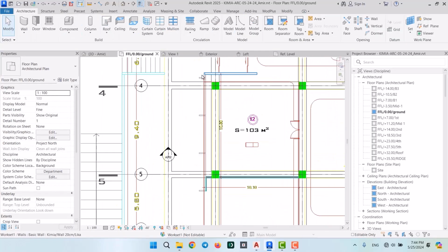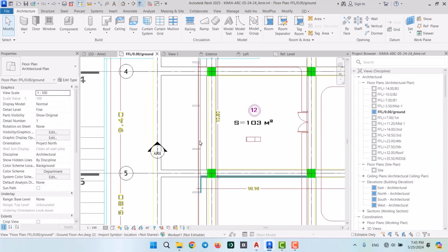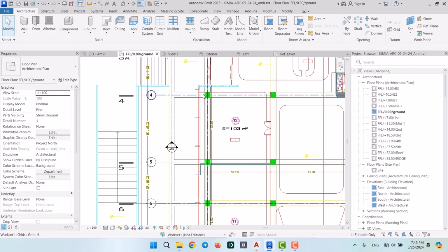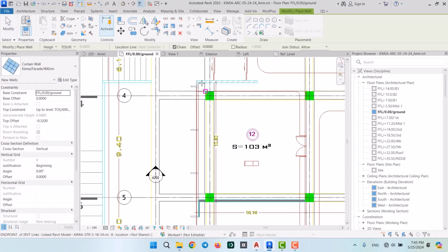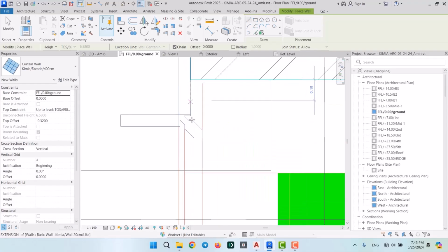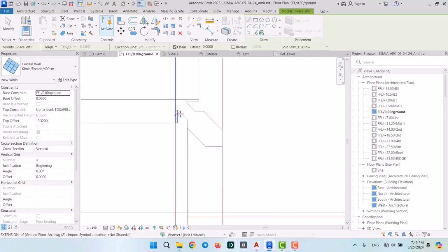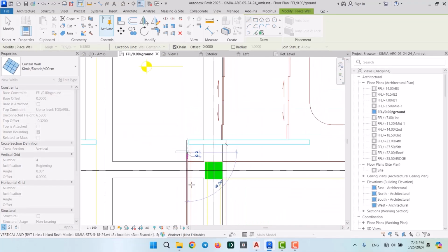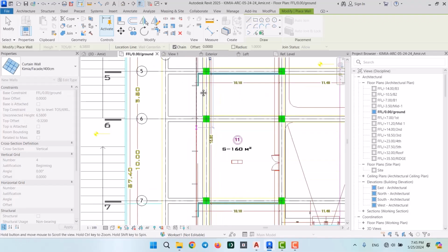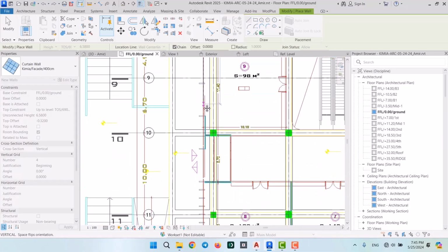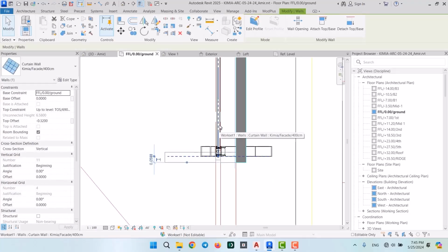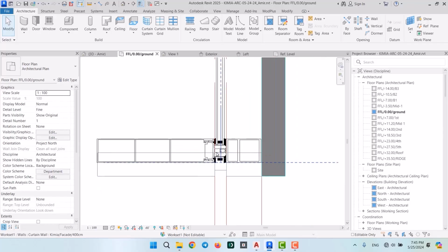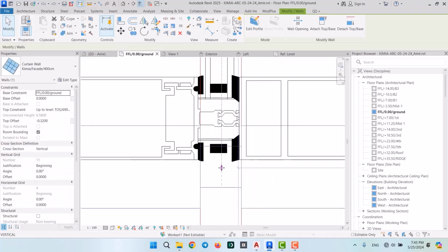Then double check one more time. Now you see for this area for which we're going to be placing the curtain walls and the mullions, we said that the spacing between each wall was 4 meters. So I'm going to go over here and begin from this corner. For example, from here. Then I'm going to go all the way down to this point right here. Alright, now it's also facing the wrong direction, so I'm going to press the space bar to rotate it.